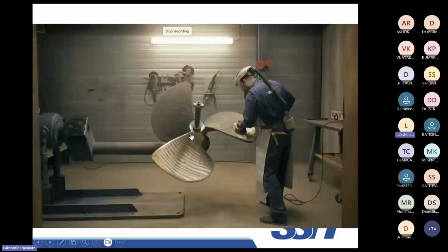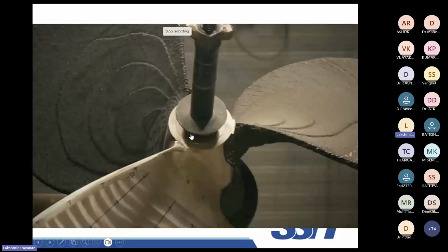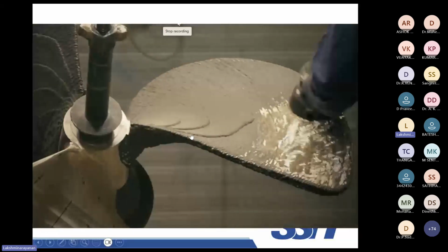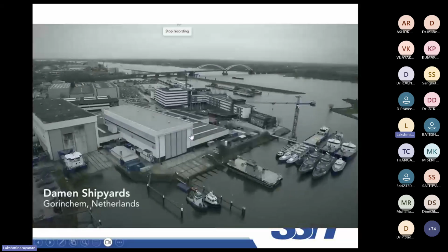This is a very popular material. Nickel aluminum bronze is very popular for ship propellers. Especially, these are made by the casting process, which involves a lot of issues, like porosity control is very difficult. Since it is a casting, the cooling process is very slow. It involves grain growth, and other defects like the grain size being very big. The phases present in that material, if you look closely, are around 4 to 5 phases, what we call kappa phases. You can just search nickel aluminum bronze, you will understand that.